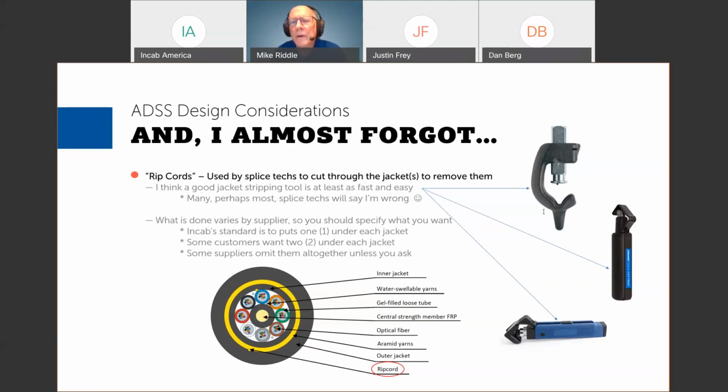So let's see. How would you avoid wet tube to space potential? Okay, next question. How would you avoid this issue when cables are close in underground systems? Well, okay, today is really supposed to be talking about ADSS, but I will answer the question. You have the same problem. So if it's an underground circuit and you put a corrugated steel armored cable in it, you're going to have significant induced voltage and current on the armor. And of course, in theory, you can just ground it. In practice, there's more to it than that.